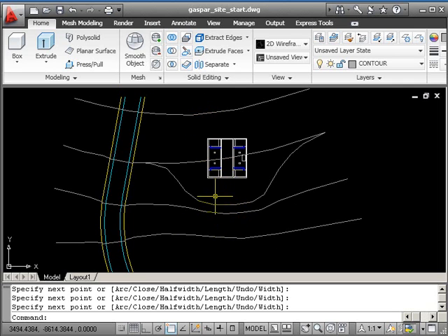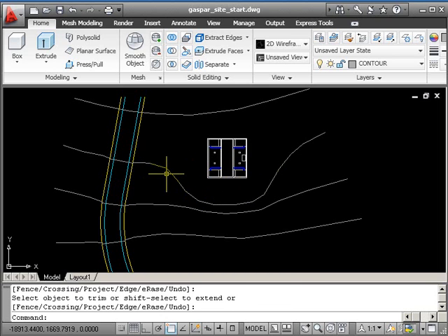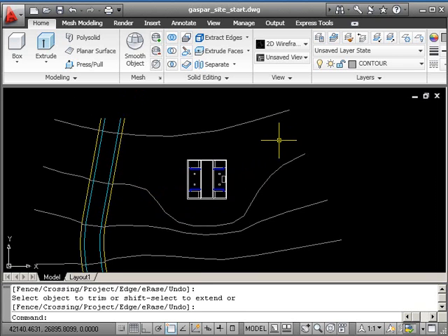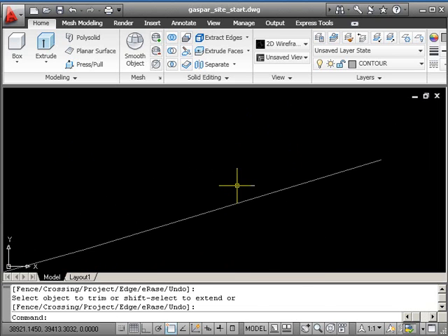So effectively that's got quite a good view. And that's how this kind of works out. You're able to understand the shape of the ground just from some lines. So I'll use the trim command to chop away that bit. Now it's useful if you put some heights on the contour so we know what the level is. Now they could be relative to each other, so you could say 0, 2, 4, 6, or what we usually do is put in the real height in meters.